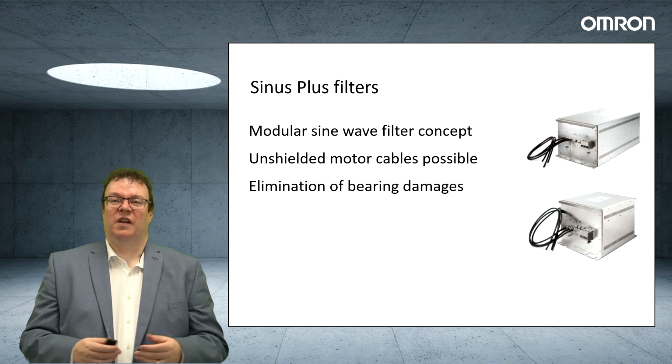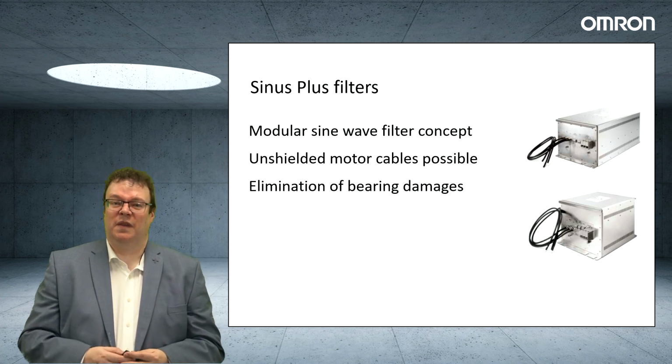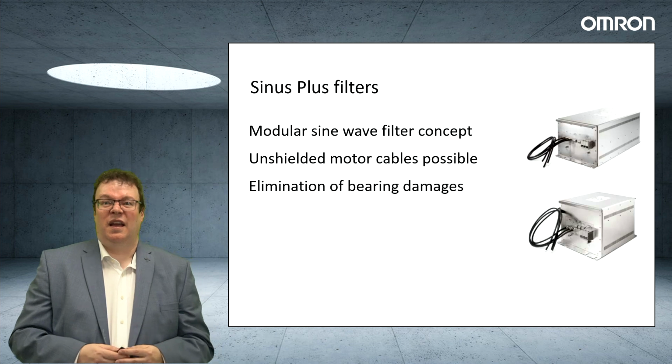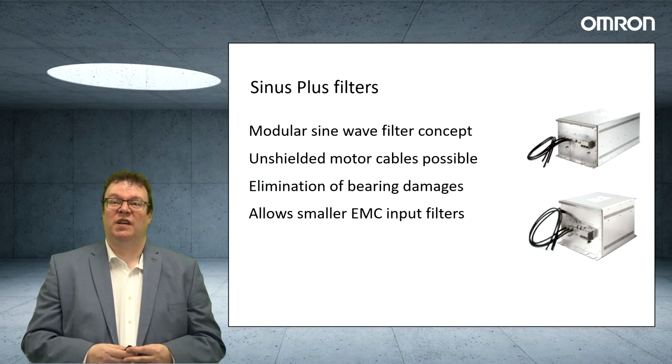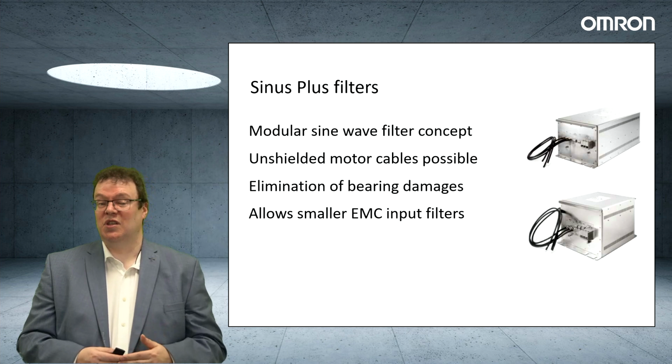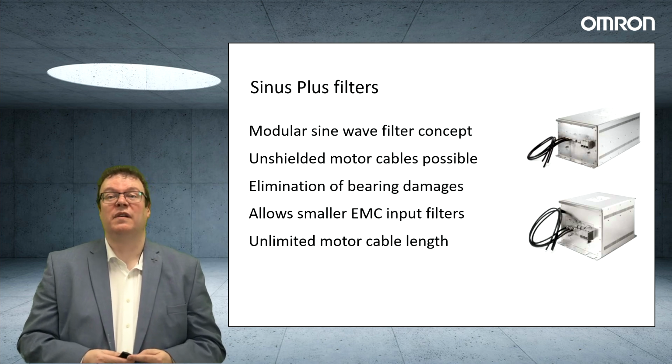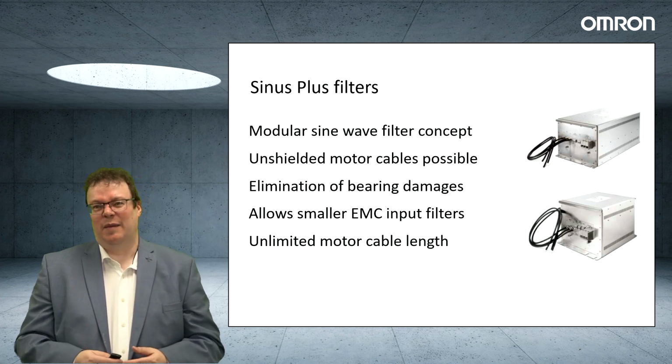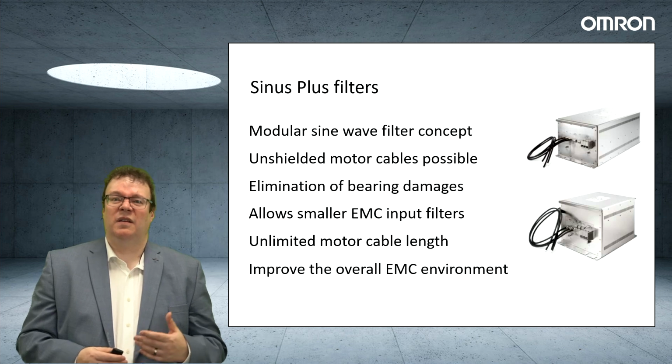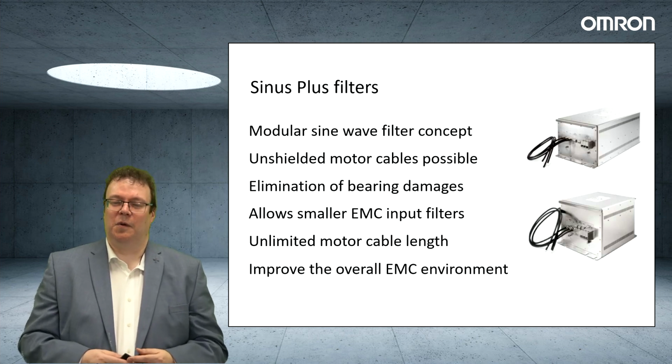This allows the use of unlimited motor cables, and they can be unshielded. It eliminates any risk of bearing damage. It allows you to actually use a smaller EMC input filter on the other side of the drive, and as I mentioned before, an unlimited cable length. This does a lot for improving the overall EMC environment.